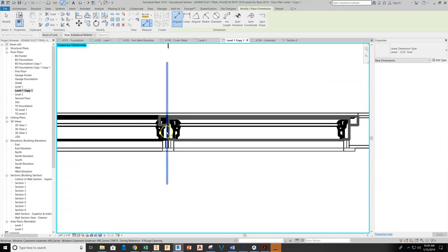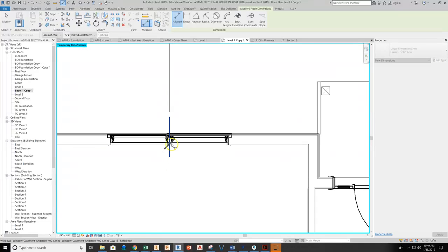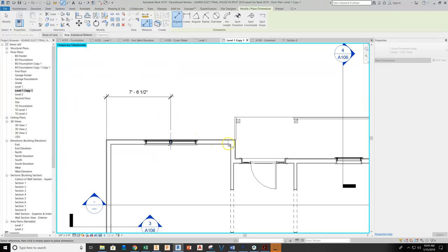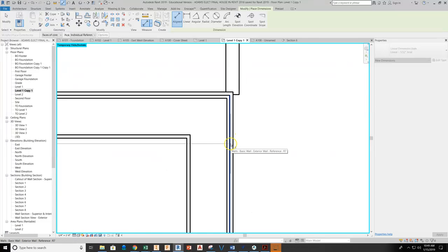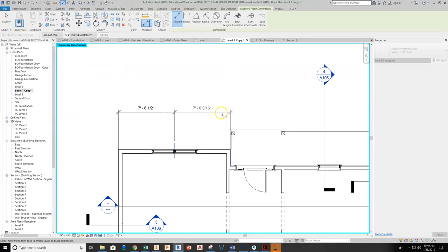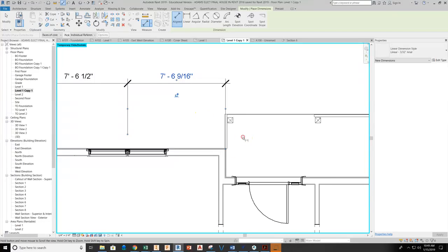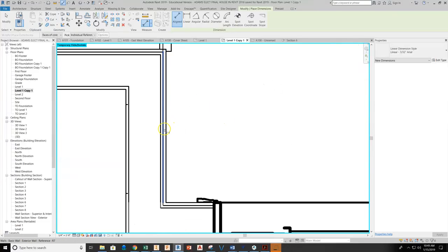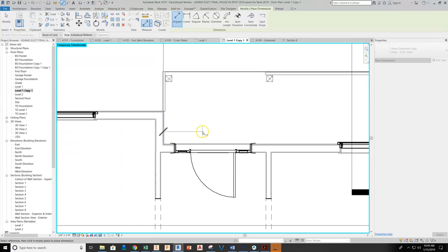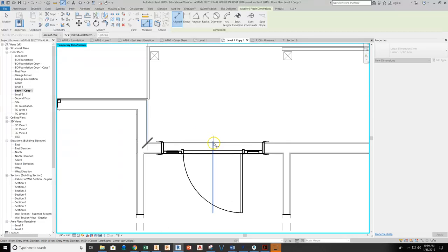I'm going to zoom back in here and find that same point on the window, for the center of the hole, and then since this is an outside corner to the front porch, find the sheathing face. I'm going to pull out and drop that. If in your particular dimensioning standards you go to the stud face for the outside of the walls, that's fine. I would just highly recommend noting that on your drawing on the title block.